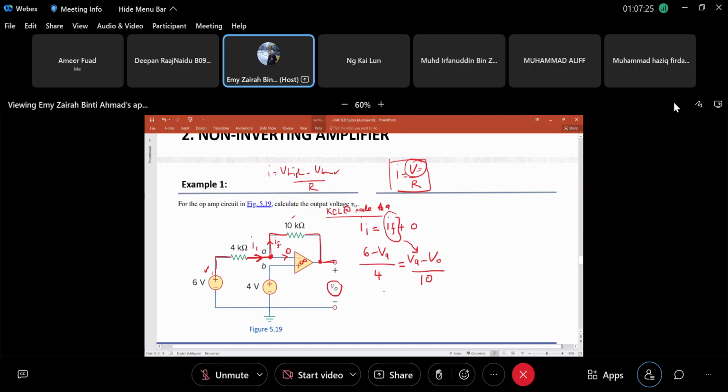And the next thing is you need to know VA equals VB. Always remember, once you have derived in voltage form, you need to see that VA equals VB. This is important, or else you cannot move forward. So VA equals VB equals what? VB is 4 volts. The understanding of VA and VB, you can just memorize it. VA must equal VB because it's an ideal op-amp.